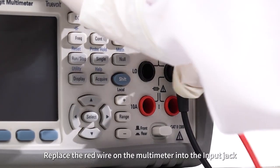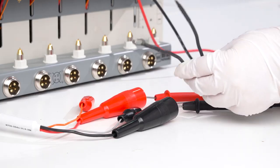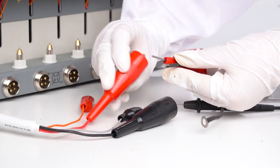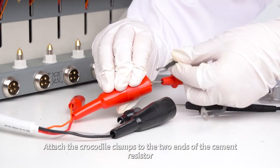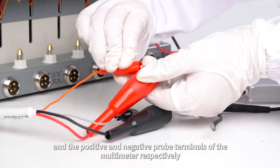The next step is to calibrate the voltage manually. Replace the red wire on the multimeter into the input jack. Then, connect an external cement resistor. Attach the crocodile clamps to the two ends of the cement resistor and the positive and negative probe terminals of the multimeter respectively.